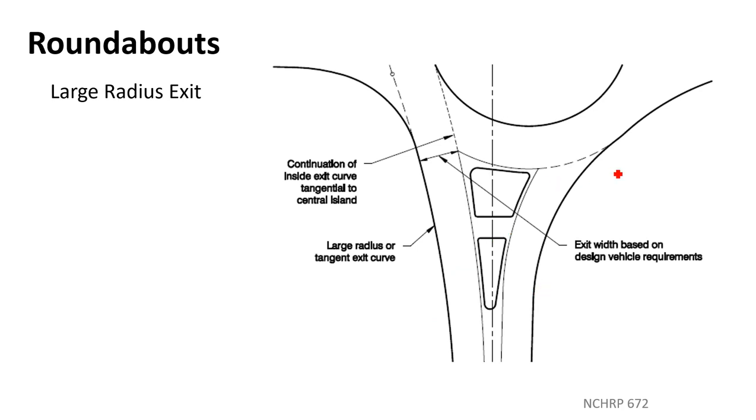This is a much larger radius one, and it just depends on this one. You can see the center of that island is probably about right in here, and here are your offsets. Remember, we had 3 different styles. Here's that center. So this one, the entrance side, is offset to the left from the center of the island, right? So there's your offset. This is really good for deflection on incoming cars. It's really bad for deflection on the exiting or outgoing cars.